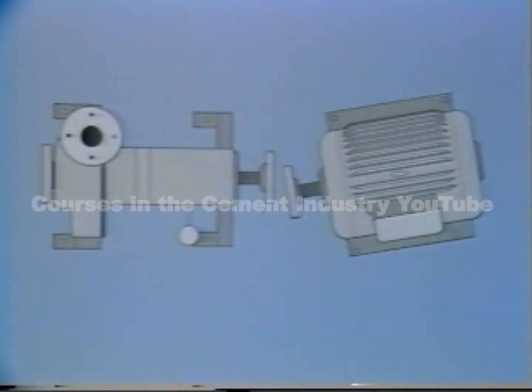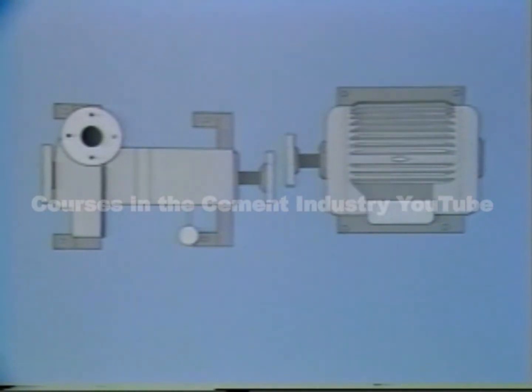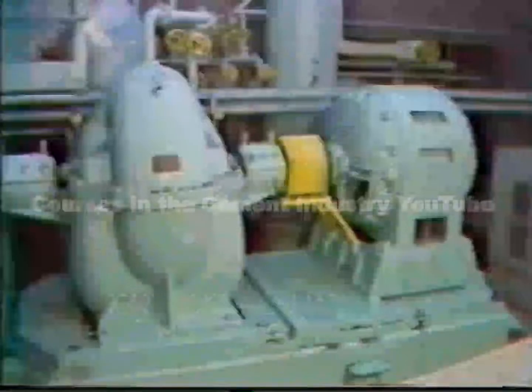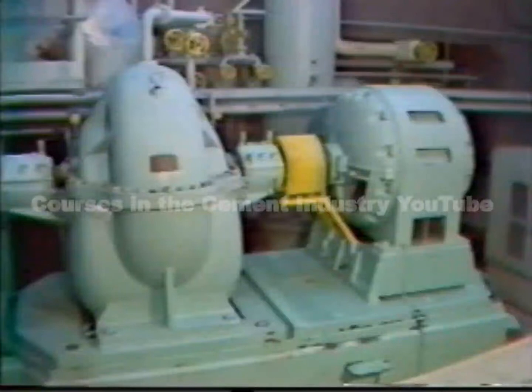Let's get back in alignment now and see the other type. If the whole motor is shifted one way, like this, or the other way, like this, we have horizontal parallel misalignment. And of course, you may find a combination of angular and parallel misalignment in the horizontal plane.